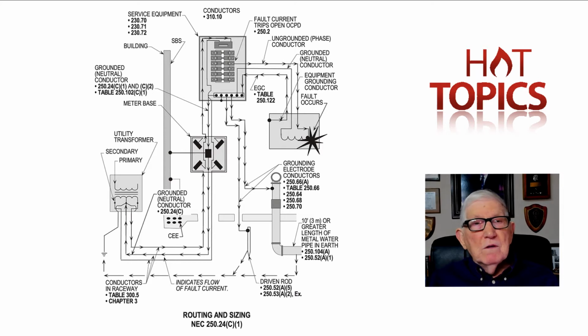But if you should develop a restriction somewhere in that raceway run, then that equipment ground will pick it up. You'd say, well, what do you mean? Say at a connector somewhere, and we're just saying this, that a resistance developed due to loose connections, not tightened couplings or whatever, or punched out rings broke loose, whatever, and say that the metal conduit would only pull 70% of the fault, then the equipment ground would pull 30%.